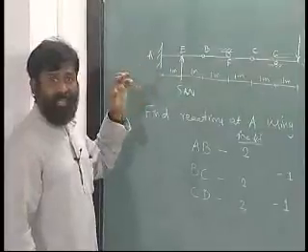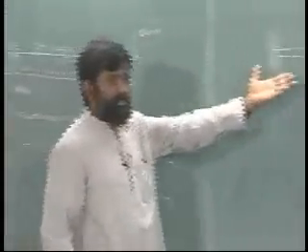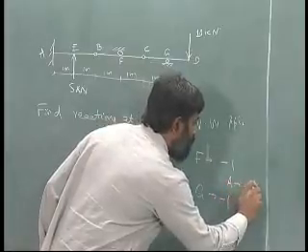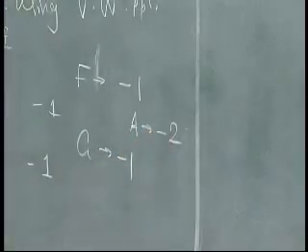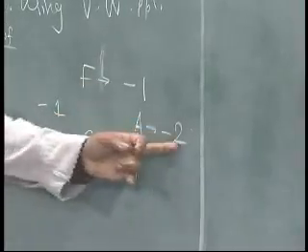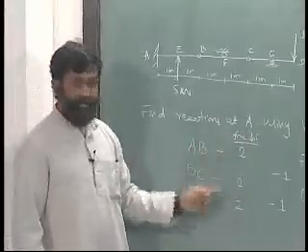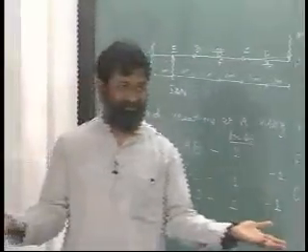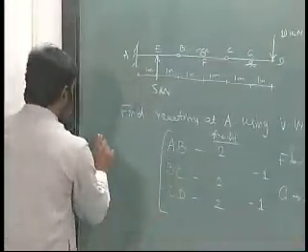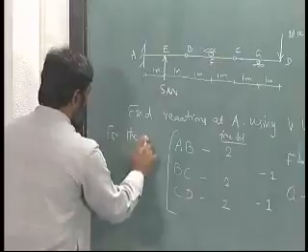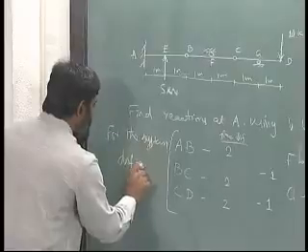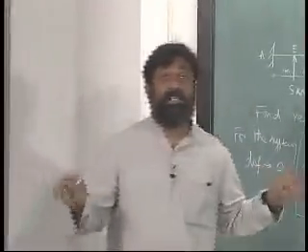How about A? A I have arrested, like what we have done here, we have arrested both rotation and vertical displacement at A, which means A offers -2. So let us total them, -1, -1, -1, -1, -2, total is 6. I have 6 degrees of freedom, constraints are 6, which means I am not left with any degree of freedom, okay. So for the system, total degrees of freedom equals 0, which means it is a determinate